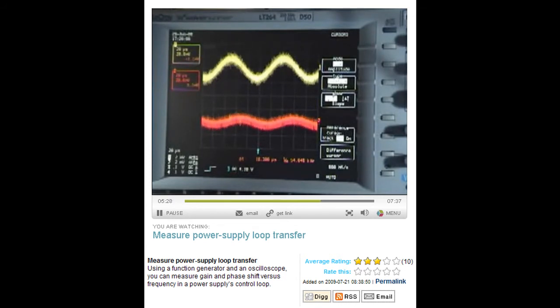And the other really interesting point of such a Bode plot obviously is the 0 dB crossover. What does 0 dB in gain mean? 0 dB means that the signal amplitude of the injected signal is the same as the signal amplitude after the signal ran through the loop.